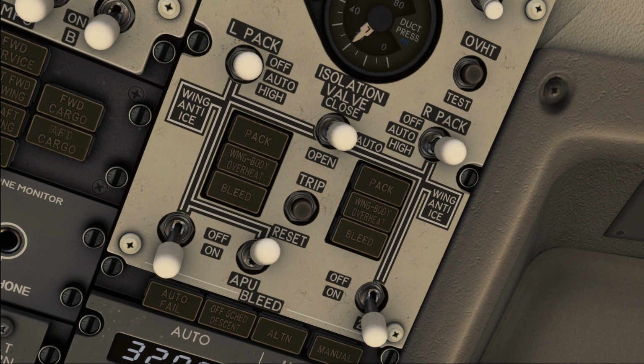In particular, once the flaps have been retracted following takeoff or go-around for at least 45 seconds, if the bleed air switches are still in the off position, then this light is going to illuminate to make the pilot aware that an incorrect configuration exists on the bleed air system, to prevent decompression from taking place as the aircraft climbs.